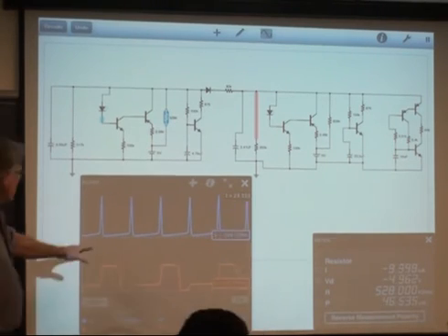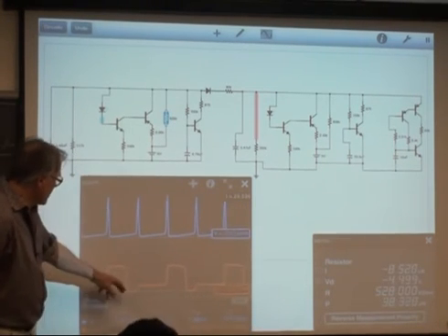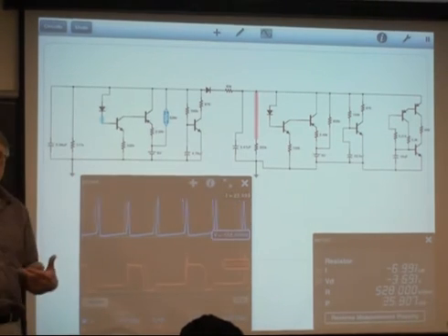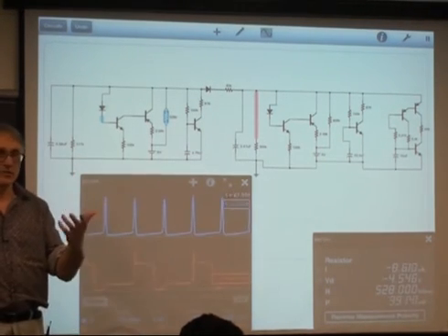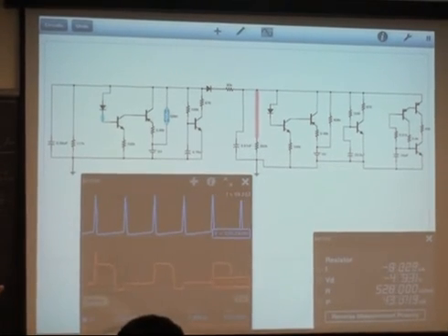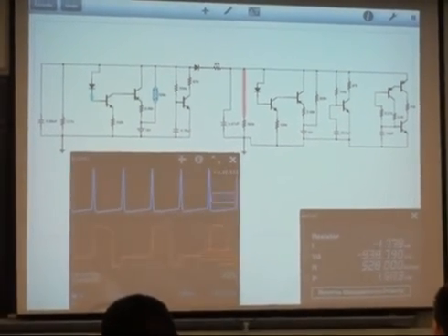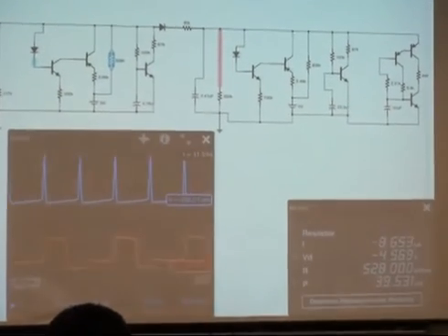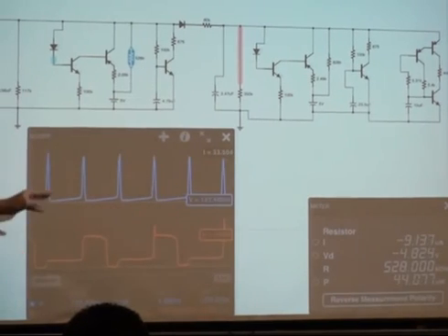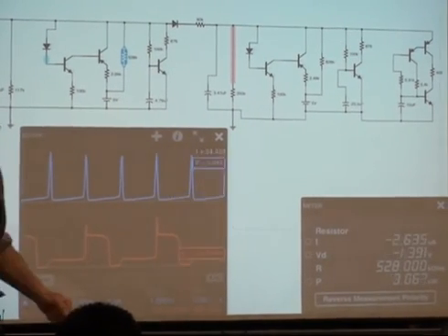So the current that's injected off of the pulse where it doesn't lock is certainly affecting the nonlinear oscillator. It's biasing it towards a pulse, but it doesn't have enough current to actually drive it to a full pulse. But it's causing the next pacemaker pulse to have enough current to drive it.